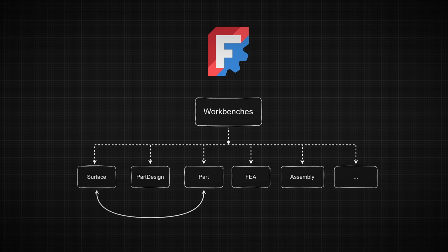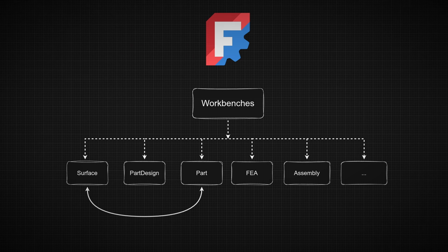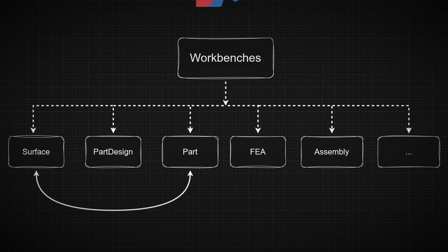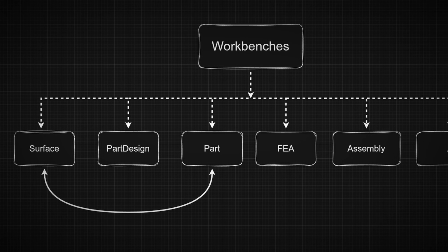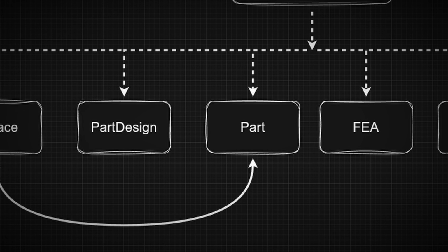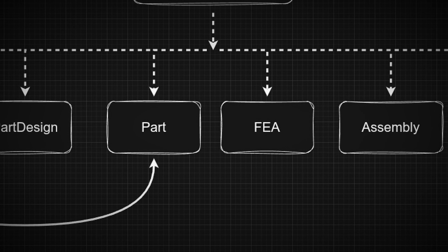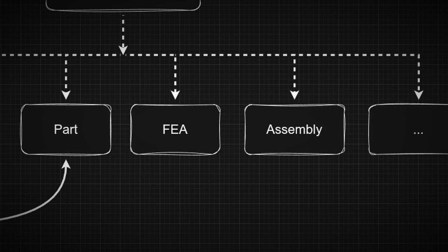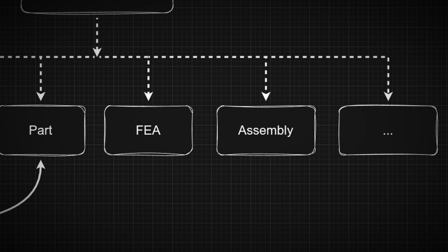Before diving in, you need to understand the core logic of FreeCAD. Everything revolves around workbenches. Think of it like a giant toolbox. All your tools are sorted and stored in different compartments. To complete a project, you'll often need to move between these compartments to find the right tool for the job. This is why it's crucial to differentiate between the workbenches used for building your model and the ones used for processing and outputting your work.